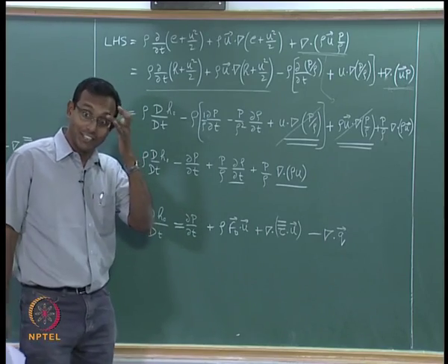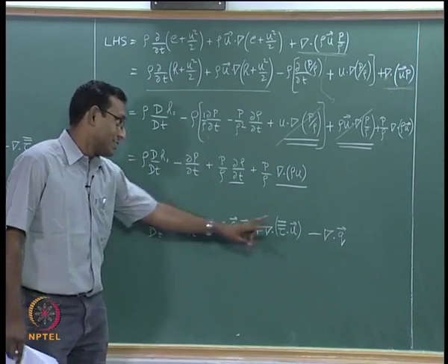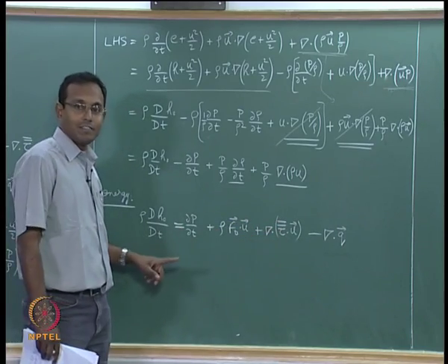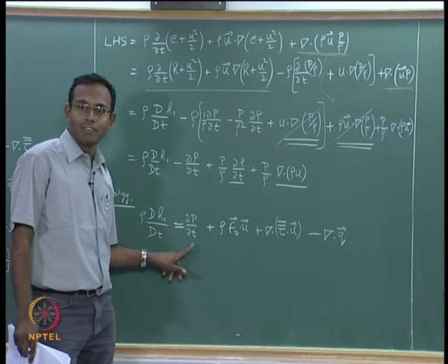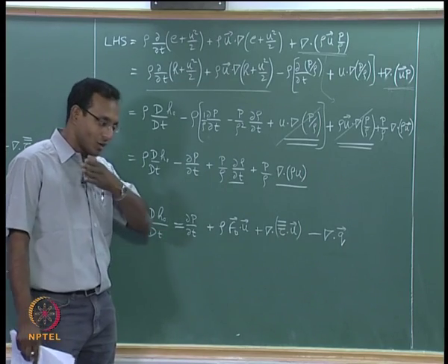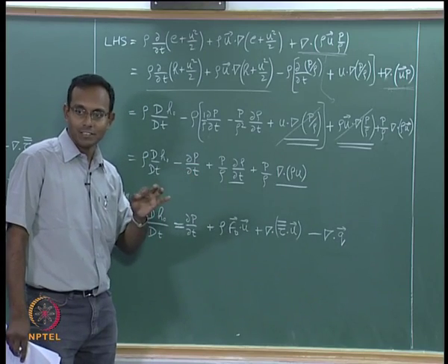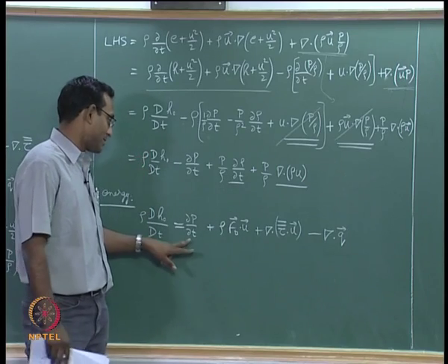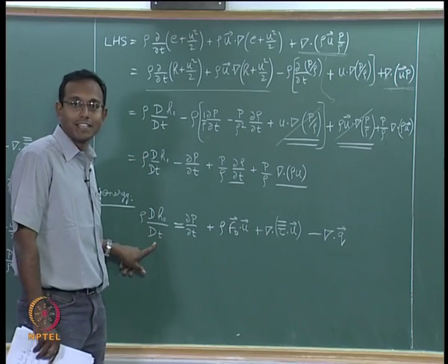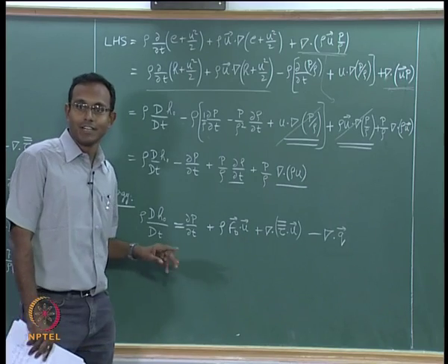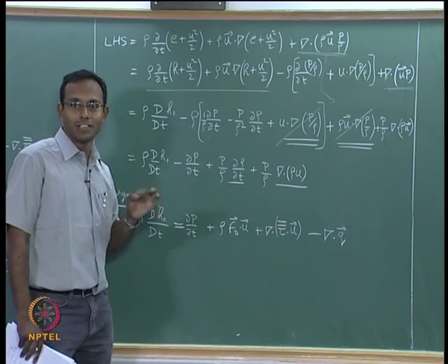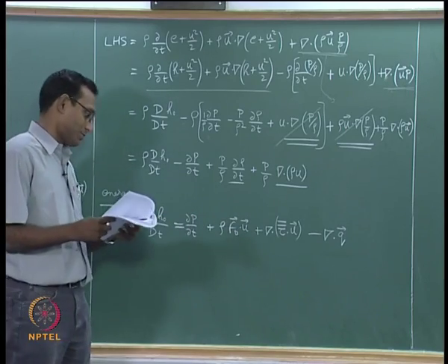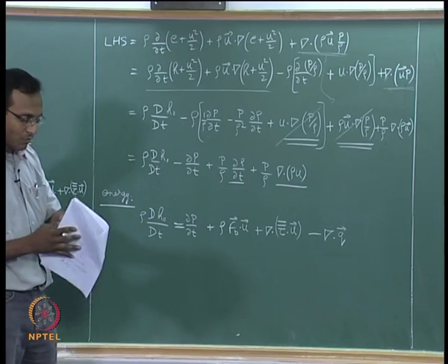Where have we seen this? We have seen one example where we said there is no heat transfer, there is no body force, there is no shear, but we have a moving shock. If we had a moving shock, then when the shock crosses my current point of interest, I am going to have pressure rising. When the pressure rises, I am going to have T naught increasing, that is how we saw, right. We found that when a moving shock crosses my point, T naught increases, that is directly coming from here. These are the various mechanisms by which we may change energy of the fluid.